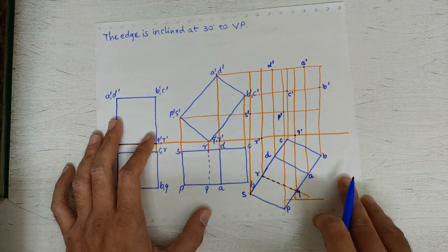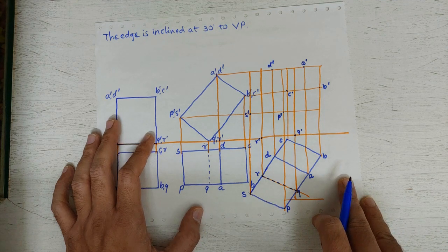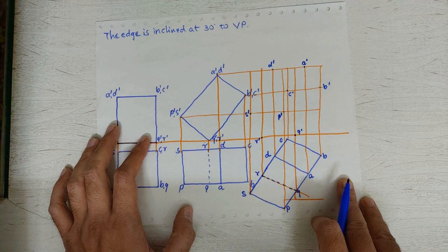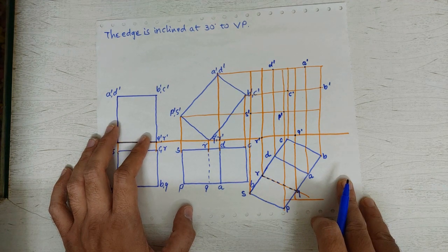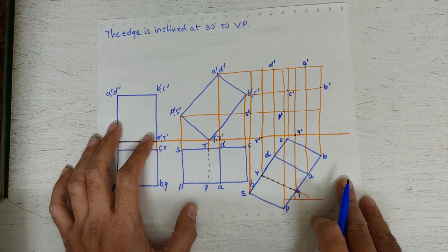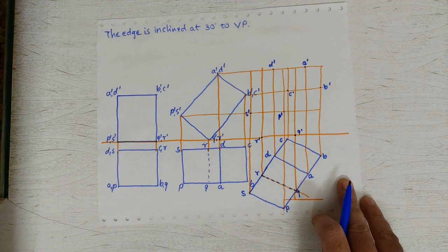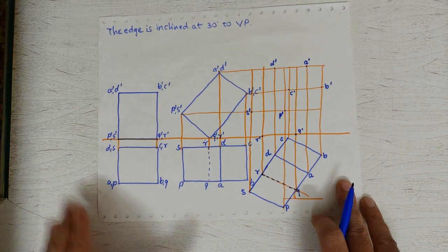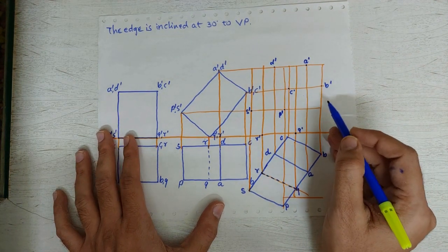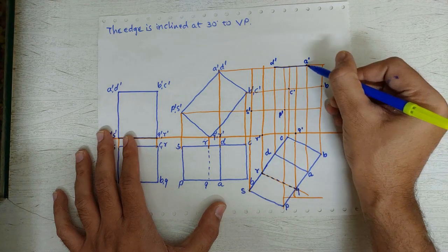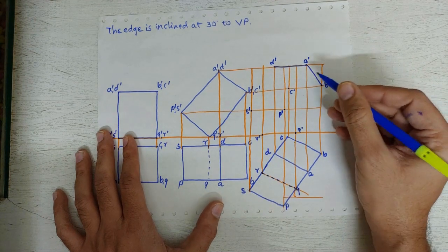Okay, so once we obtain the points, now we need to connect them, and here also we need to think about the hidden entities. So as per the clue, outlines can never be hidden lines. So what we can do is we can first draw the outline. So this is an outline, this is an outline, this can never be hidden.